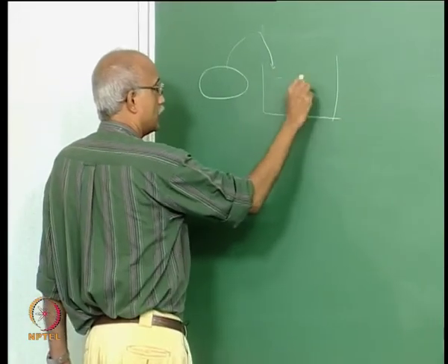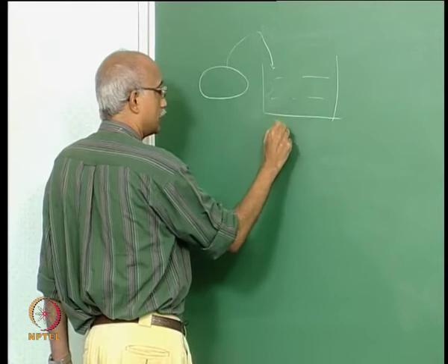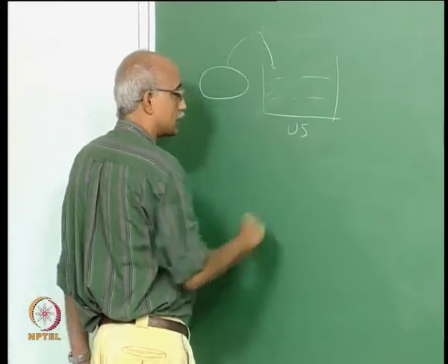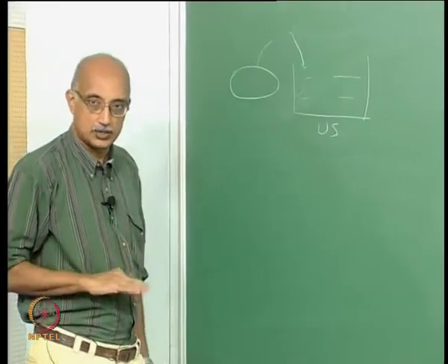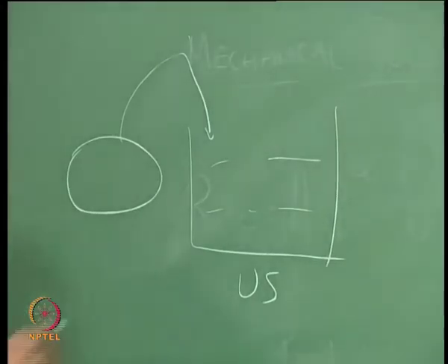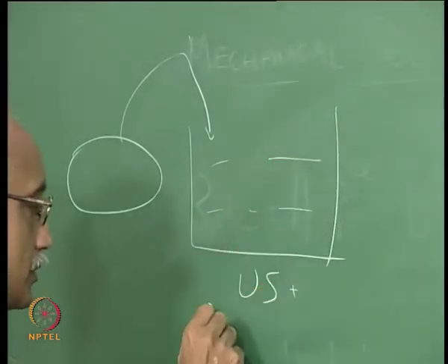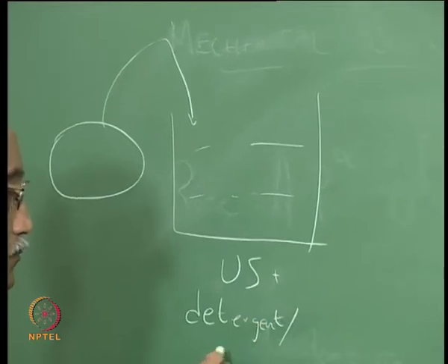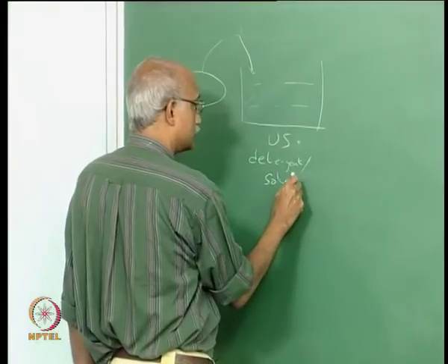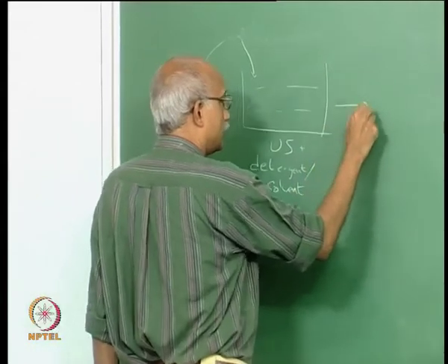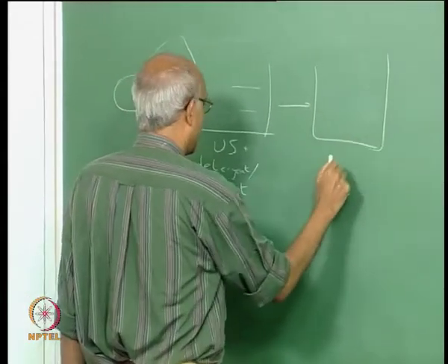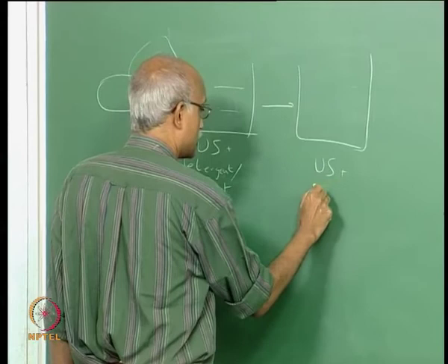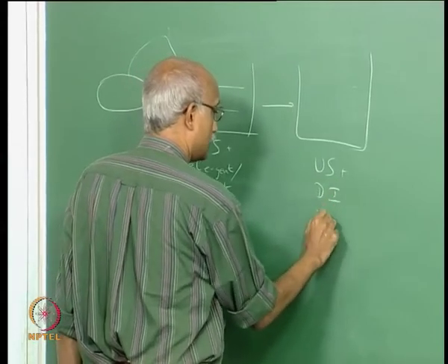So there will be one stage of cleaning where you will have some ultrasonics attached to the tank, and then there will be some detergent or solvent, and then it will go into another ultrasonic bath with just deionized water, for example.